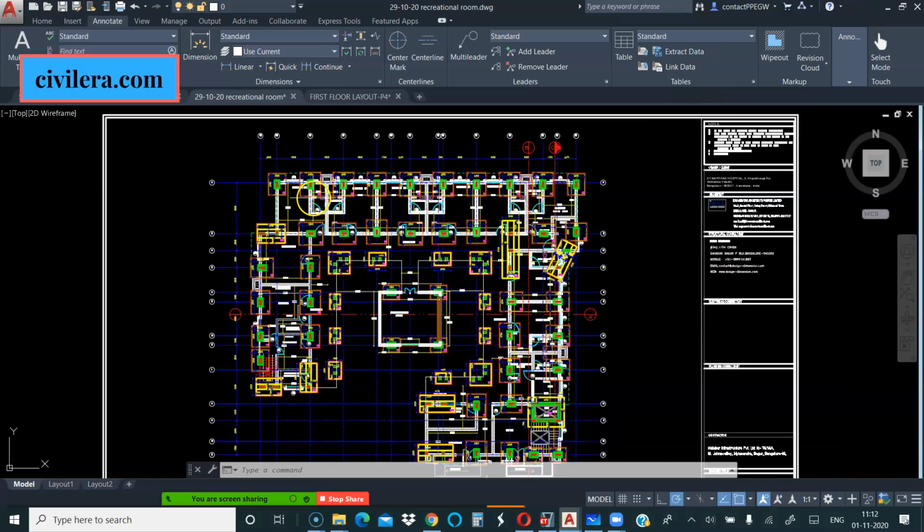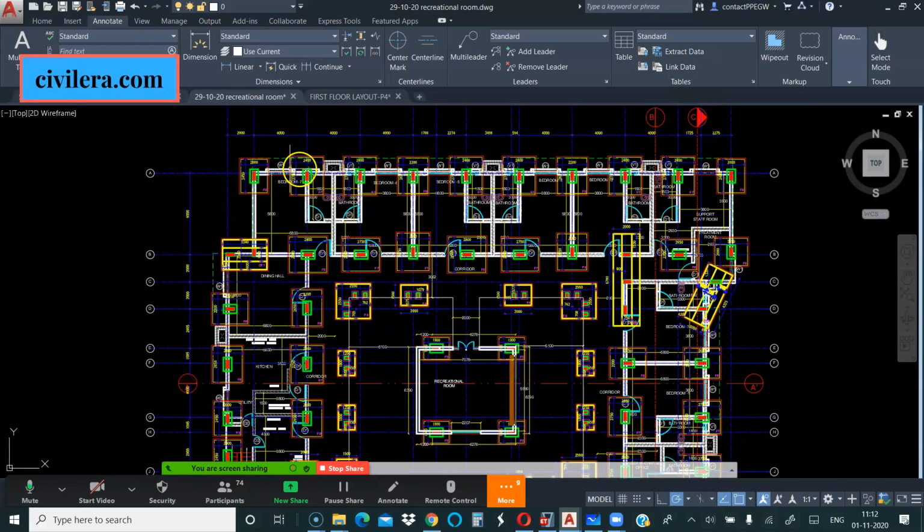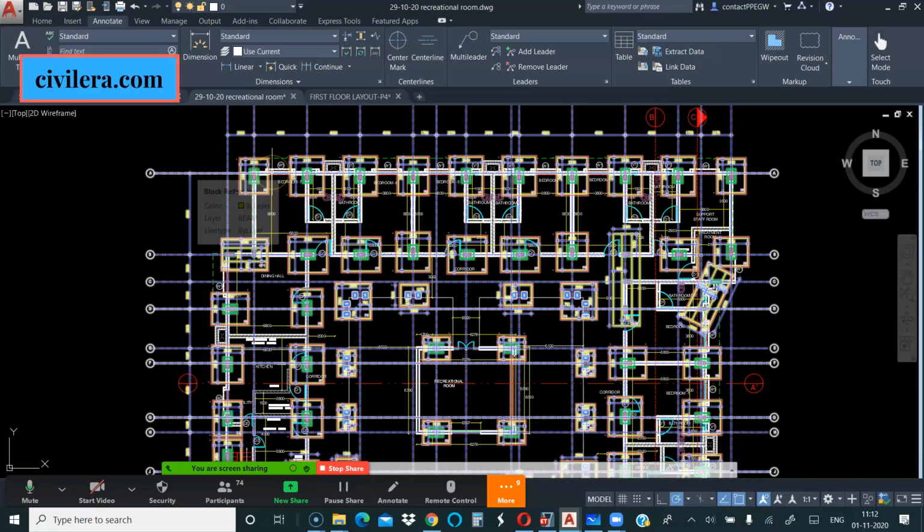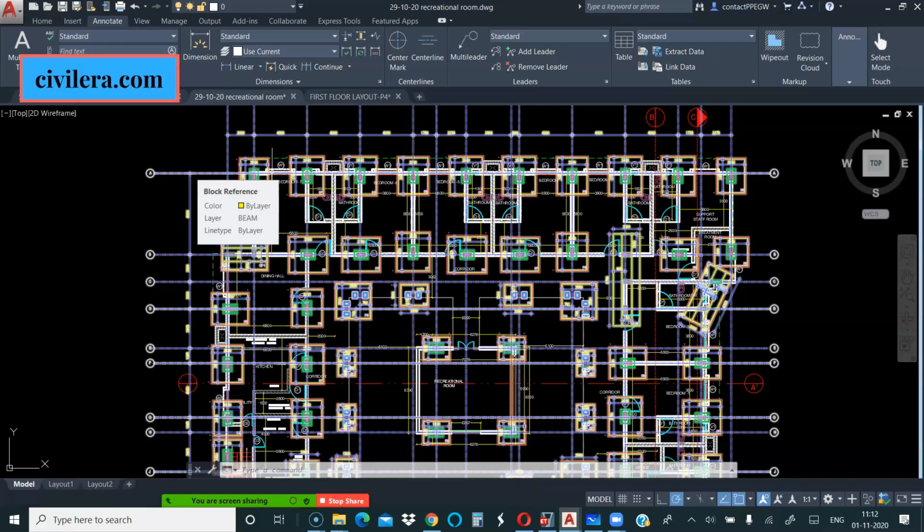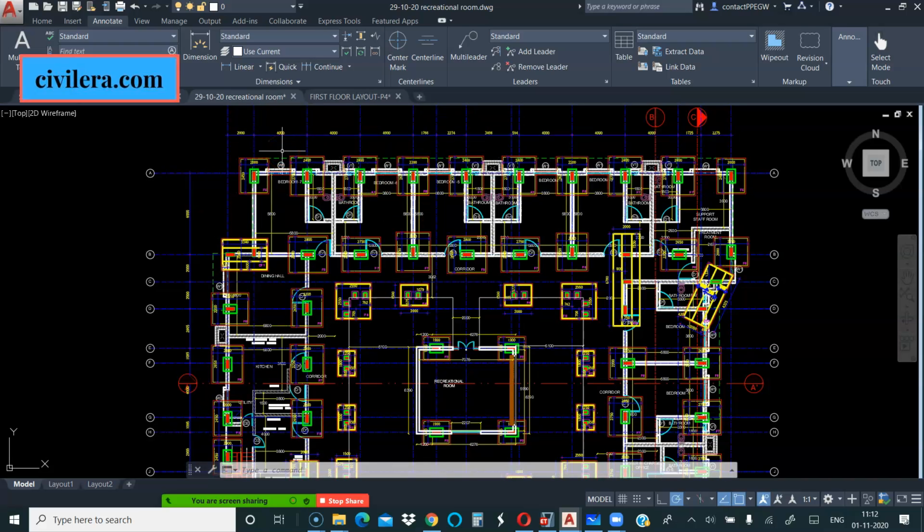Then coming to sizing, I don't want to give you any rule. There are many rules. If you even Google, you will get Pu by fck BD. You keep around 0.6 max and then size your column with Mu by fck BD square of around 0.05. That should be fine. But I would suggest you iterate it. You can easily do that with ETABS. You give a start point with your experience.